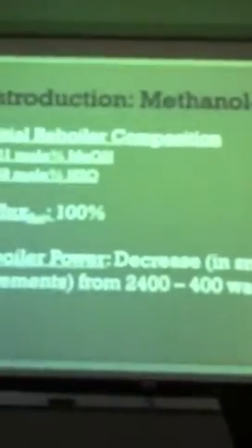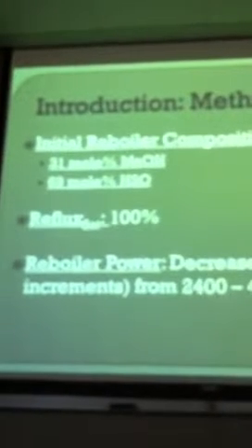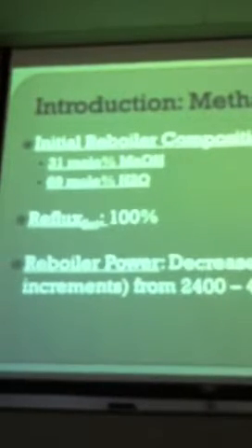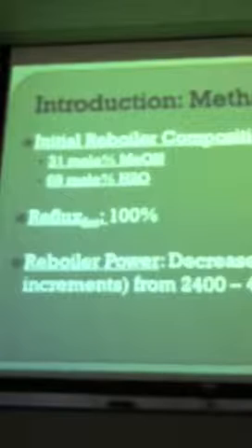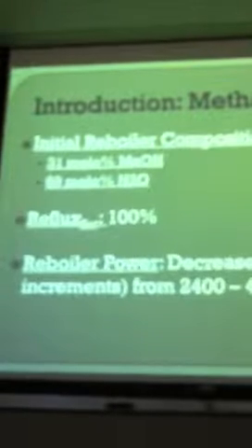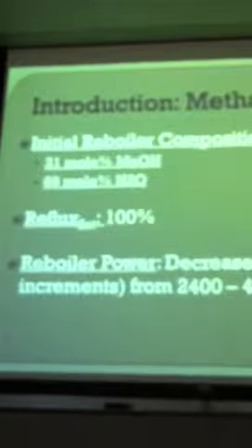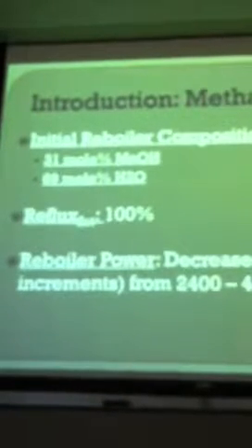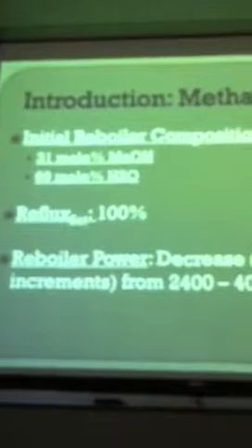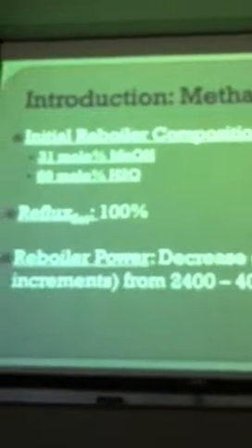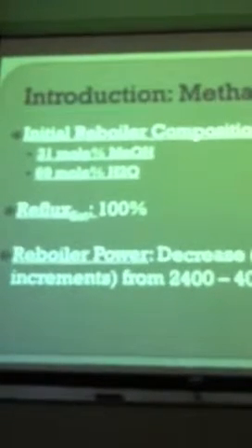So it's 31 mole percent methanol, 69 mole percent water. We set our reflux to 100%. I think this is the last 100% reflux experiment that we've done. We started off at 24,000 watts just to get the system boiling, and then decreased it in kind of random increments all the way down to 400.